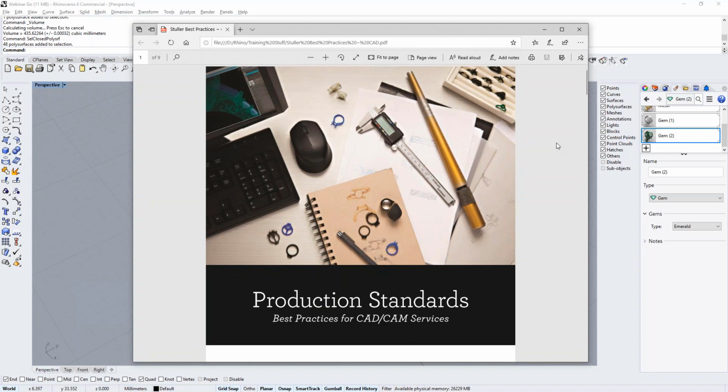As I said earlier on, Travis and I are in this discussion right now about the idea that I came up with, that it seems like with my system, which is an older DLP printer, the scale factor for the shank, for the ring size, is different than the scale factor for the bezels that I make. I use about a 1.1, 1.2 scale factor to get the ring size exactly where I want it for printing. And I use up to a 3% scale factor on smaller objects like bezels, with the 0.4 millimeter offset.